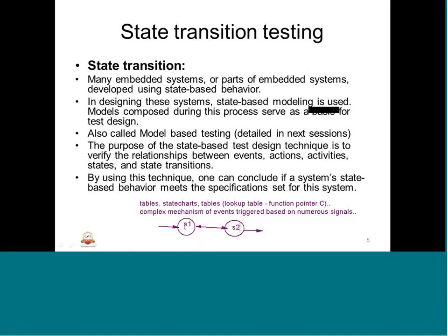Suppose state 1 needs to be entered, so there are certain events, E1, let's say, or E2, E3. Under satisfaction of one of the events or all the events could result in entering into state 1. Suppose let's define state 1 as initialization. So upon power up, there are certain conditions. Power up is one condition. The system will enter into init state.